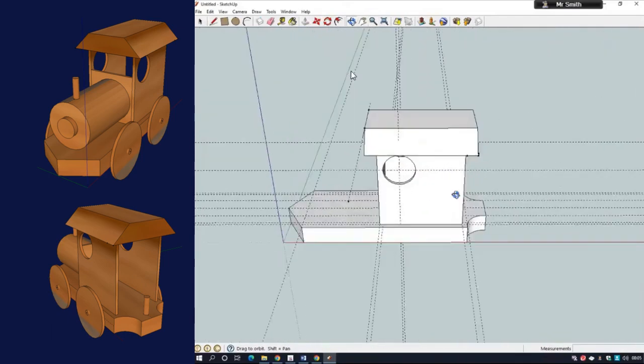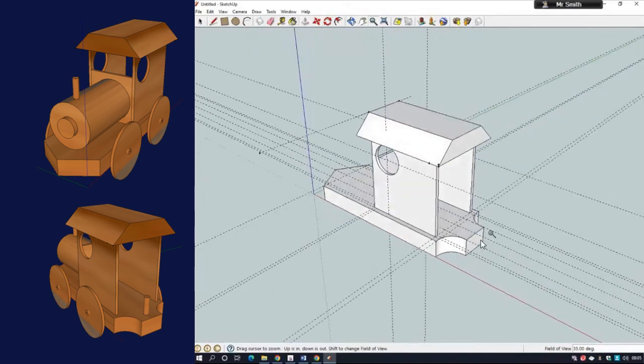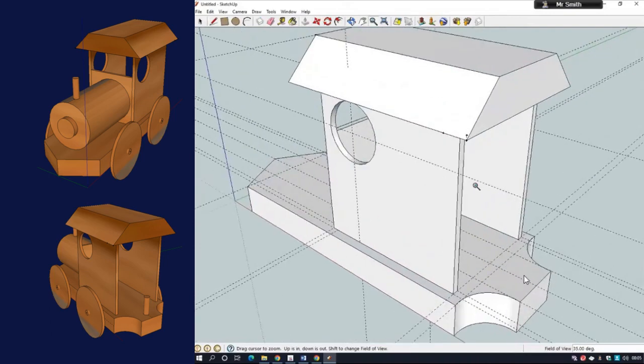Okay. So the next thing I'm going to do is I'm going to draw a little bar coming up from here, which will be where you'd attach a trailer. So I'm going to position it 10 millimeters in. Okay, I'm going to use the circle tool, click on the center, drag out, type in 3 millimeters, just a small little piece of doweling. I need to click and then only once and then drag up, and then type in 20 millimeters.